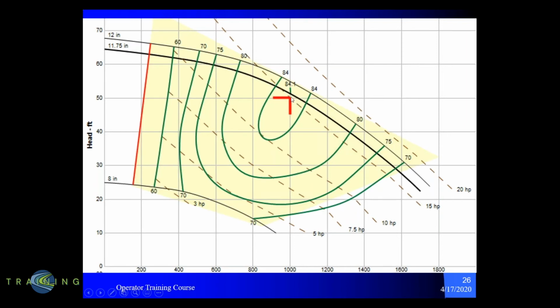So we selected a curve, we selected a pump, that when trimmed, fits at a very, very good point for our duty point, very efficient and in the middle of the curve. So this will be a very good selection.